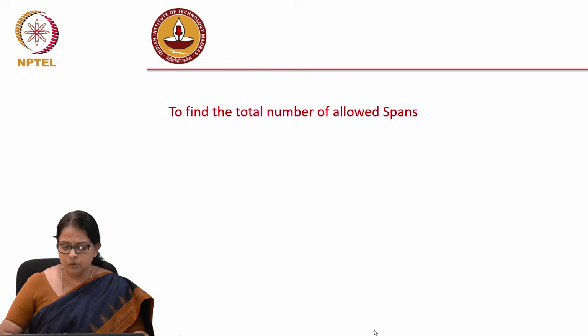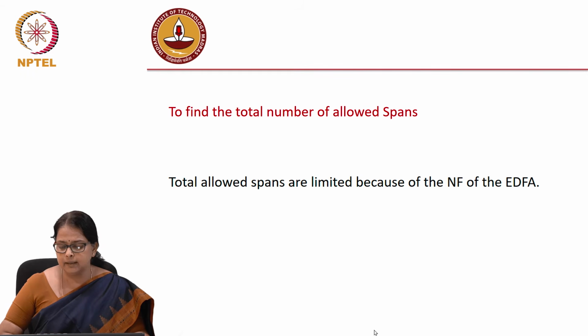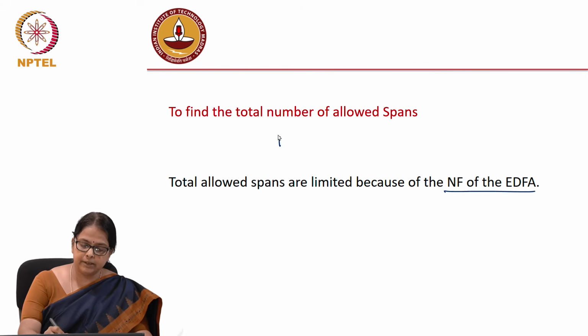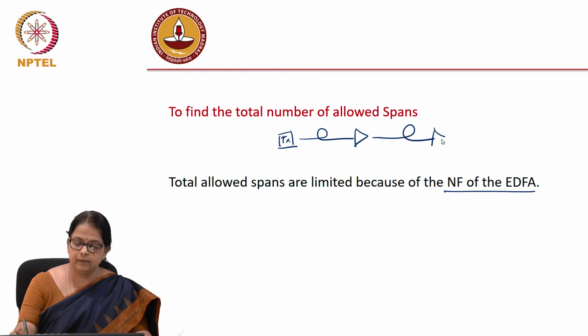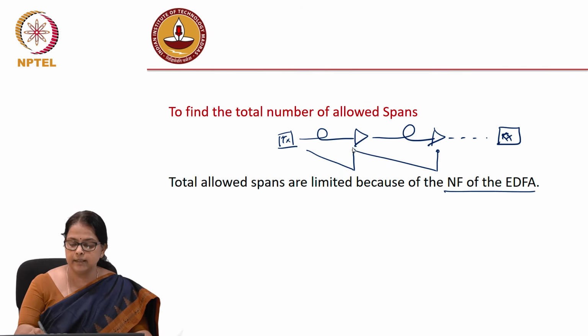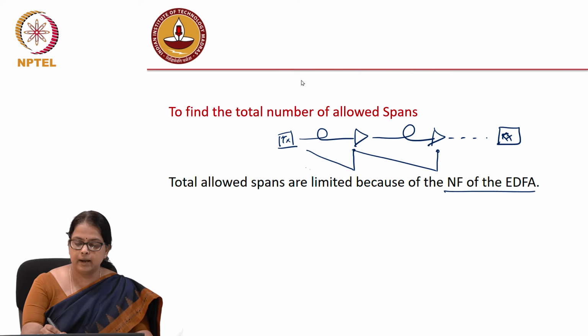Okay, so the total number of allowed spans is limited because of the noise figure of the EDFA. You cannot imagine that you can keep introducing EDFAs infinitely, even receiver. So even after assuming dispersion compensation, because every EDFA compensates for the gain, but it also adds noise.